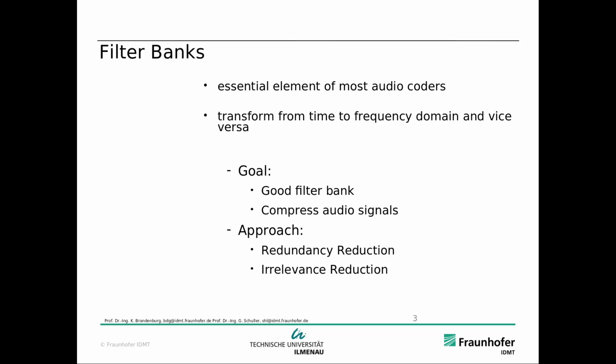And that means the subbands at the higher frequencies only contain very low energy signals, and that can be encoded with fewer bits, right? So just doing the subband decomposition for natural audio signals helps to compress, just alone, the redundancy, which is captured by most of the components being at lower frequencies.